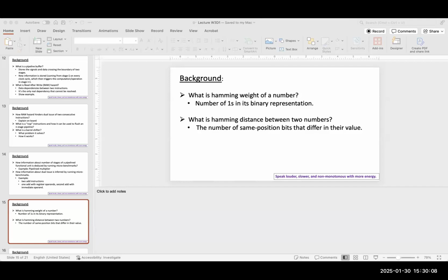But that is the case only for the first multiply instruction. After that, if you keep feeding subsequent multiply instructions, after 4 cycles your pipeline will become full, right? You will have multiply 1 here, multiply 2 here, 3 here, and 4 here. Now after every cycle, you will get the output of 1 multiply instruction, right? In the next cycle, M2 will move here, everything will move to the right. So for every subsequent instruction, you will start getting the result ready. It means that once your pipeline is full, you have a sustained CPI of 1.